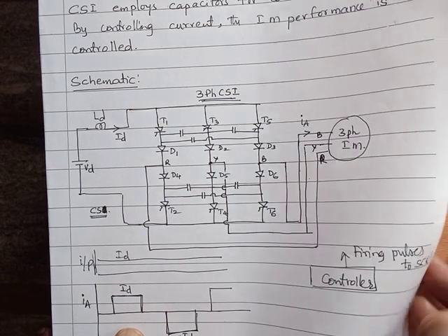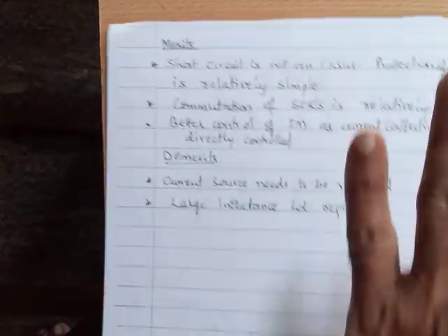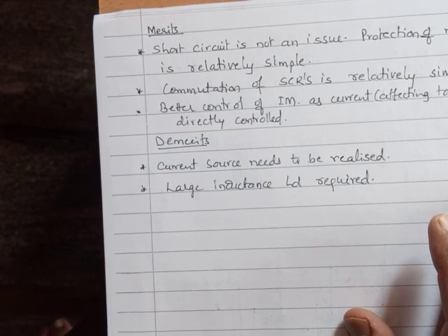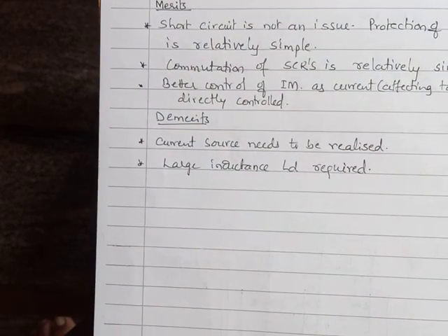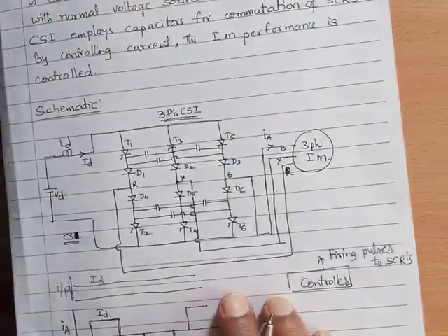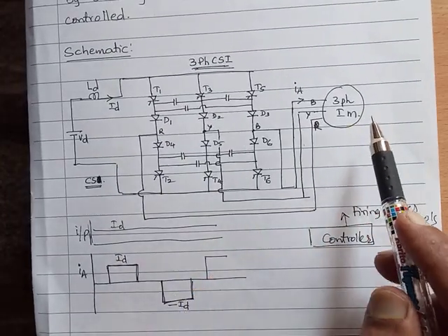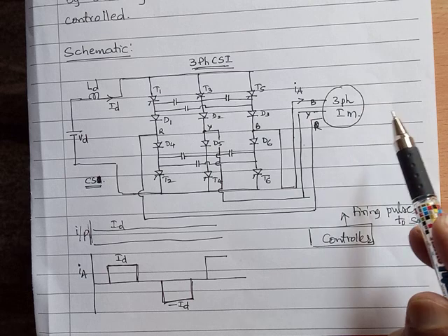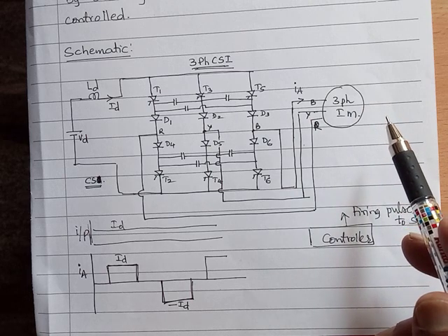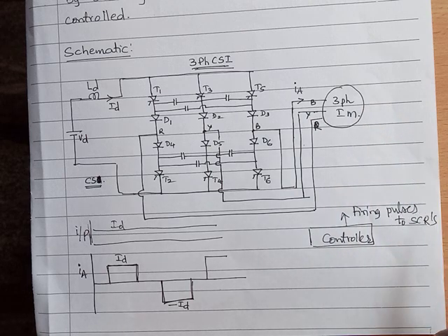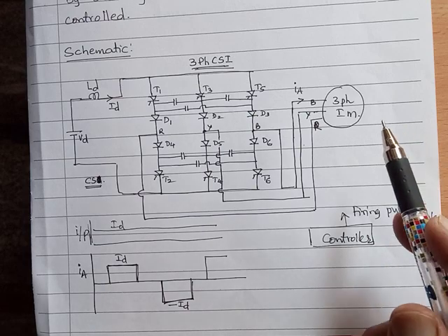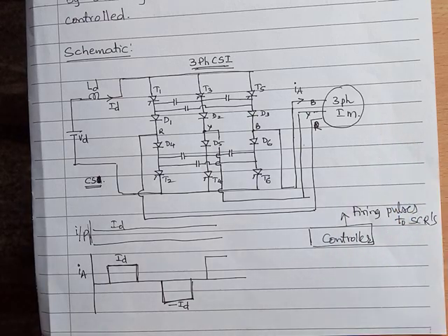Okay. So now this is fed to the three-phase induction motor, and when the three-phase induction motor is fed with this current, the effective value of which is changing, the induction motor performance will change. Depending on our expectation, we can manipulate the firing pulses, accordingly get the expected performance. Good.